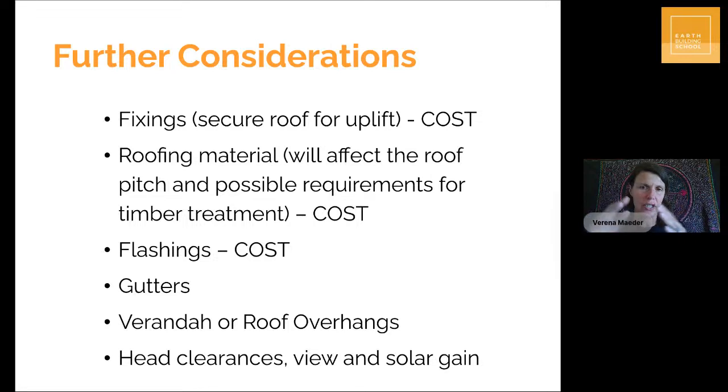So you have flashings in your roof, you have flashings around your windows, and so forth. And flashings cost money. So maybe a mono-pitched roof has fewer flashings. Maybe you want to save costs, and that would be a reason to go for a mono-pitched roof. Not saying that you have to do that, but have a think about it when you're designing,